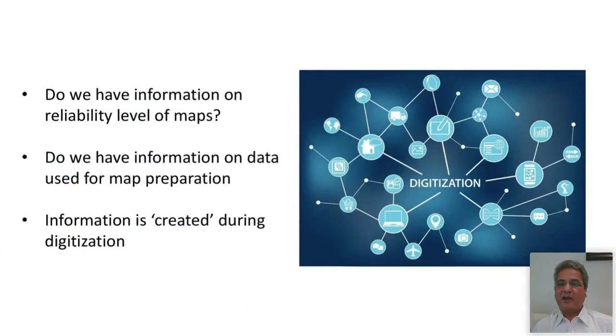Now the problem happens when this map, in the modern time, goes to a CAD operator. A CAD operator digitizes this map. Now he digitizes the road. He knows the road width is 20 meters. So he makes a line here, one edge, second edge, 20 meters is the road width. Now he has to put this water line somewhere. Whether he puts it on the left or the right or the center is completely left to his imagination. So he just puts the line there, period. So information has been created during the process of digitization, information which did not exist. Now when this digital map is delivered to you of, let's say, one particular colony, you take the map, you're working on one particular road or street, you just zoom into that area, and now you actually measure from the road edge how far is the water line.